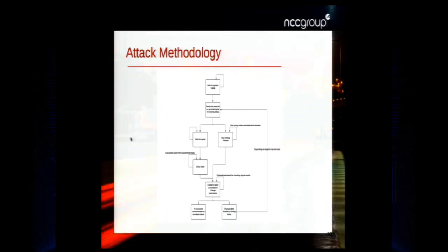Then from there, we either wait for some signal or just go through a raw timing window after this test signal is sent out. And then we emit our glitch. After that, we either wait for a sample or we restart the device and try again.